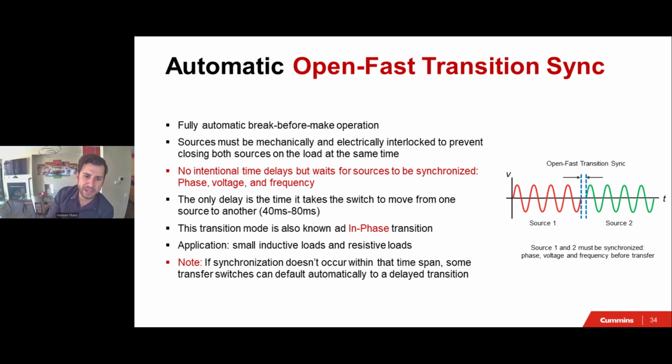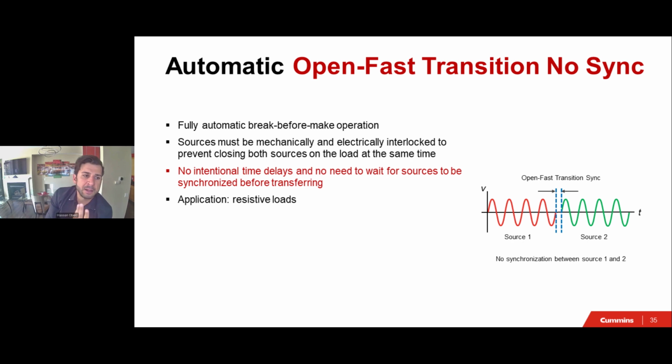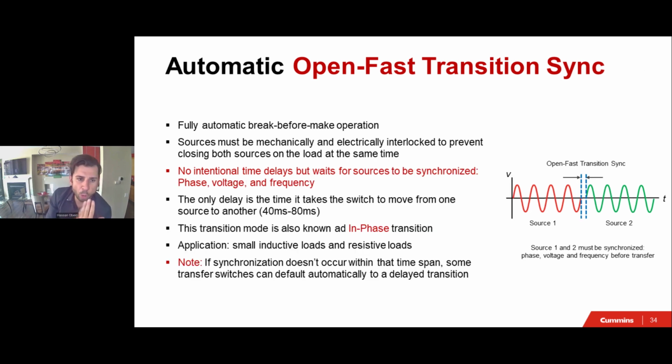And this is known as in phase. This happens very fast. We have no time delays. It's just however long it takes for the mechanism to switch from source 1 to the middle to source 2, and that's typically 40 to 80 milliseconds. The control monitors and watches when the two sources become in sync, and then it will initiate that transfer immediately.